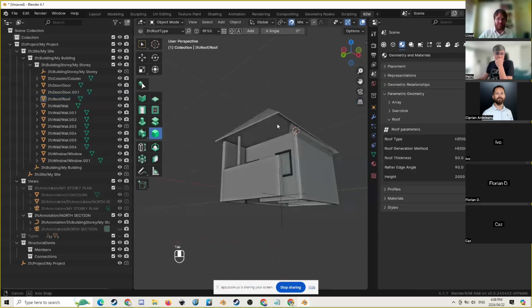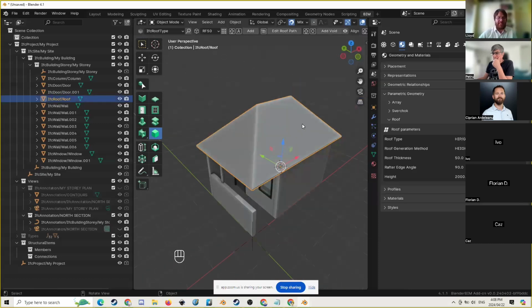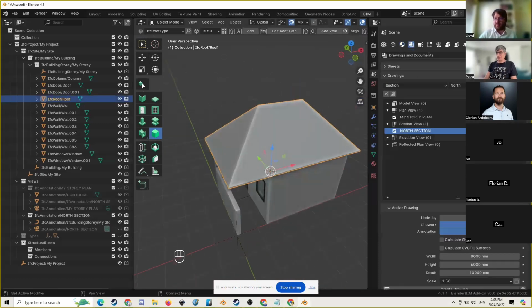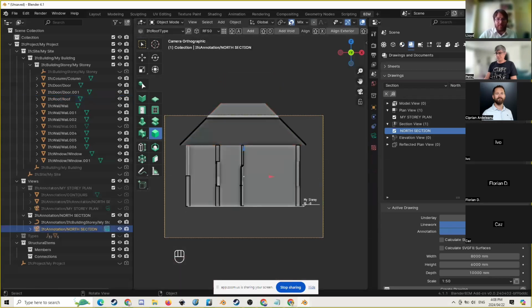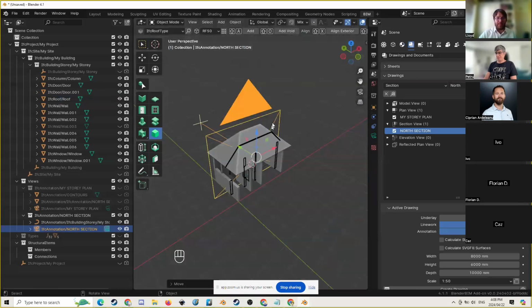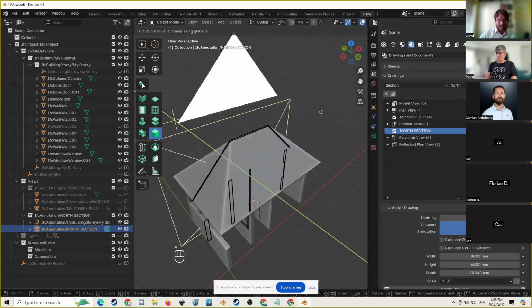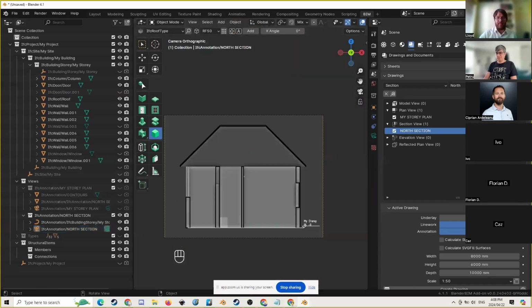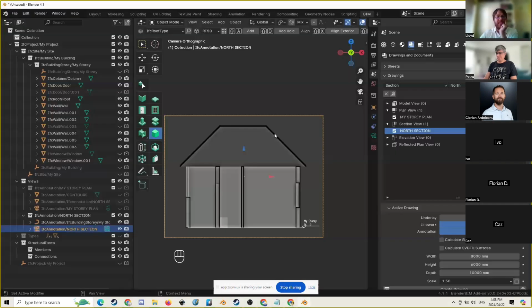There's our roof. It doesn't really make logical sense. It is hollow. So doing trusses is a different story, but also not that complicated. But there's our roof. And if we go to our section, you can see there's our roof shape as well. So if I move this up, we can adjust our section position so it cuts through the top, so it looks nice and neat. And then we can say activate and print.